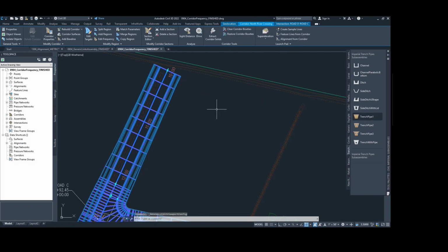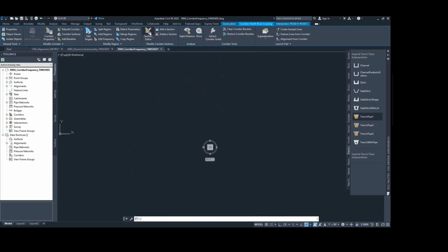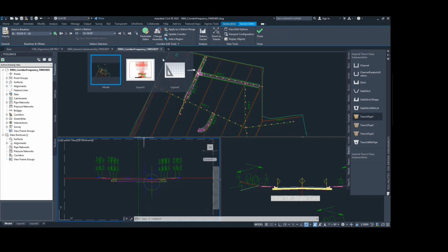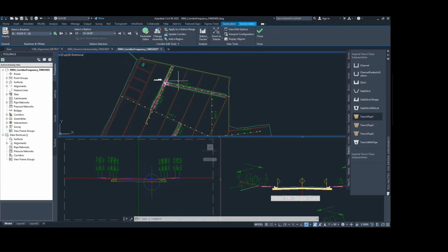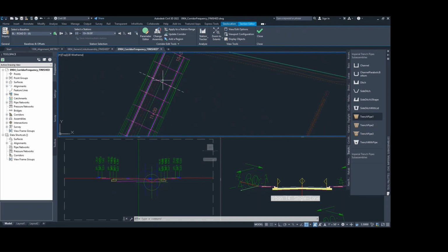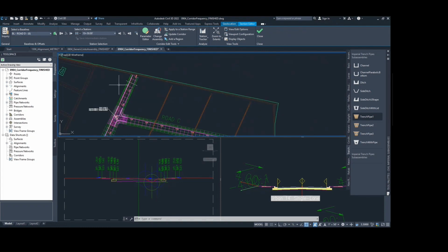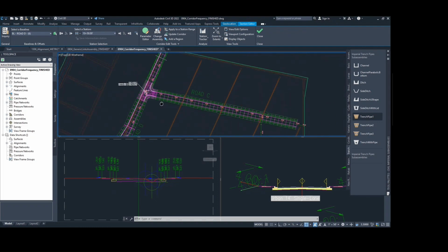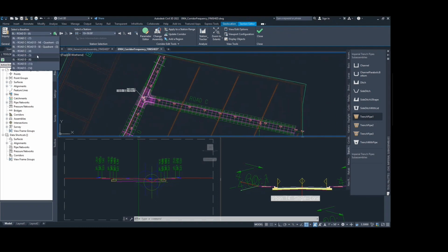And for applying this, you need to click on section editor again to apply it. And it's very important. If you forget to click on that, you will be confused. So you have one section line here on row D. This is row D, and in this station. And you can change it to any row. For example, I want to go to row C.